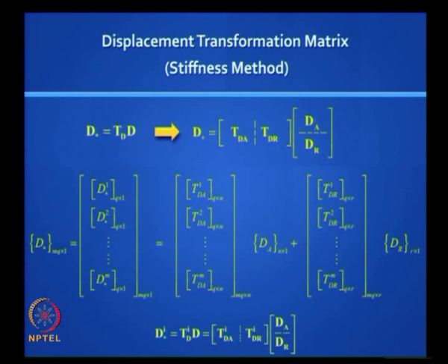Do not get worried about the size of those matrices, it is just how it works out, how it falls into play. Now I can do something here, this D star is actually including all the elements in the structure. It is too messy sometimes, so I just look at one element. When I look at one element, the ith element, it will look like this, Di star, and this TD now becomes unique to that element, so it is TiD, which can be partitioned as TiDA and TiDR. Does it make sense? This also you can do, it is actually all the Di stars put together that actually make up the D star, okay.